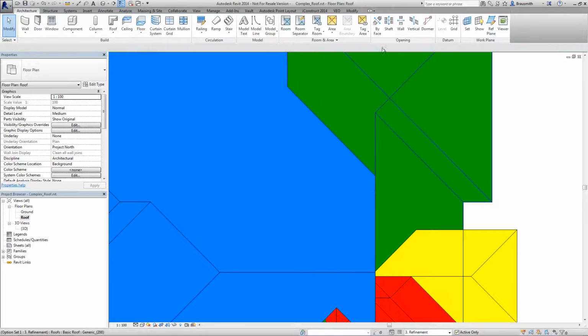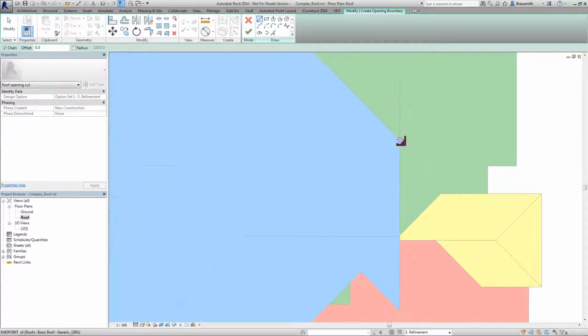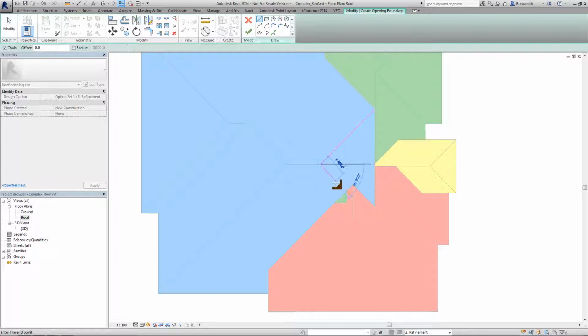And then once again, just use that same vertical opening tool to pick this, and it actually comes down in this direction at 45 degrees until it hits the ridge. Okay, comes back in, say, this direction, down to about here, across here, and then just roughly coming it back to here like so.